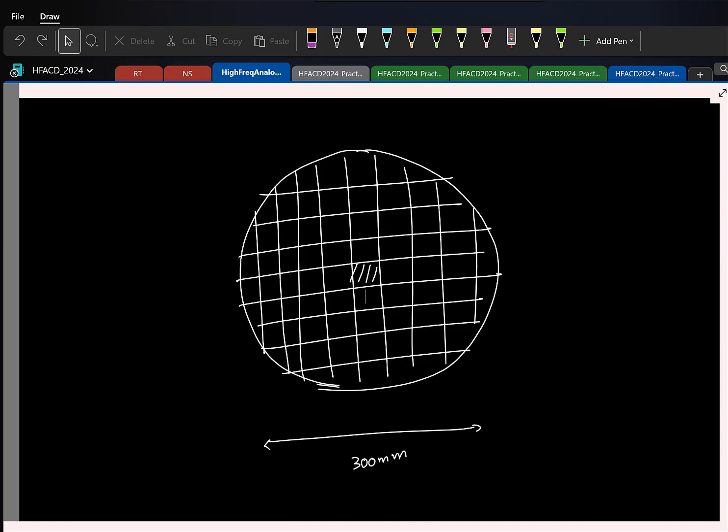So here, let us say I consider this chip. I found that the resistors have a mean value of 1 kilo ohm. Now let us say I took a chip from this corner. Here, if I find the mean value of all the resistors, you will find that need not be 1 kilo ohm; that could be, say, 1.2 kilo ohms. Similarly, if I take the chip from this corner, here it could be some 0.8 kilo ohms.